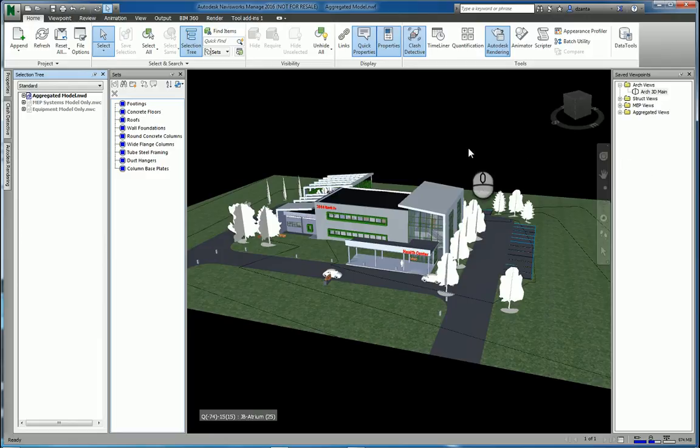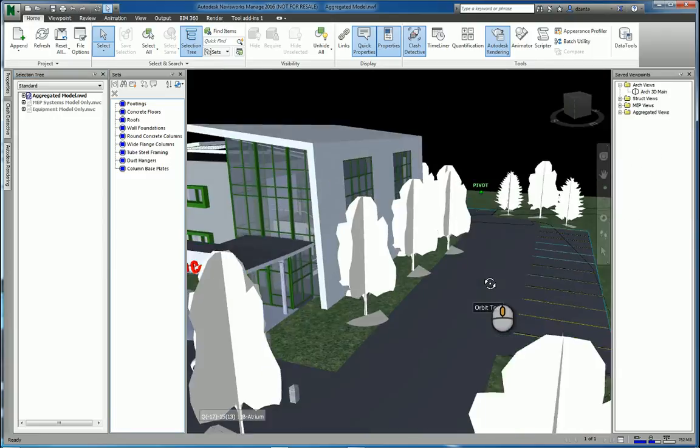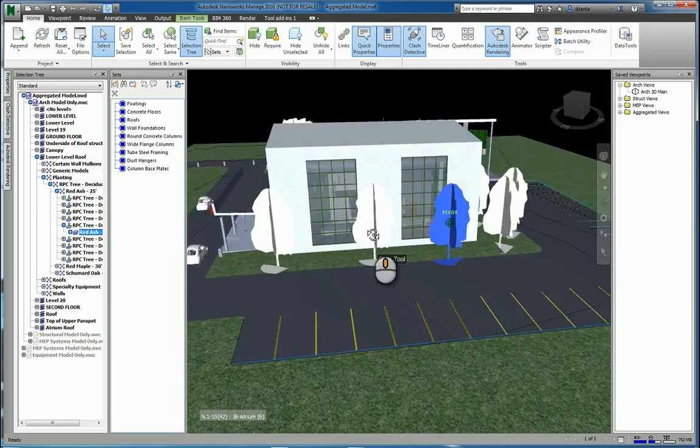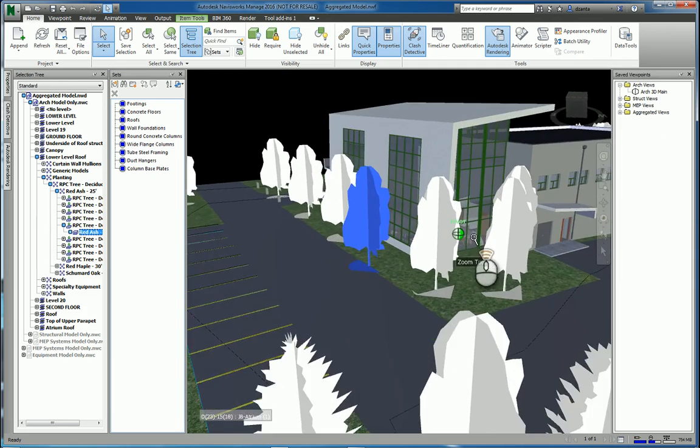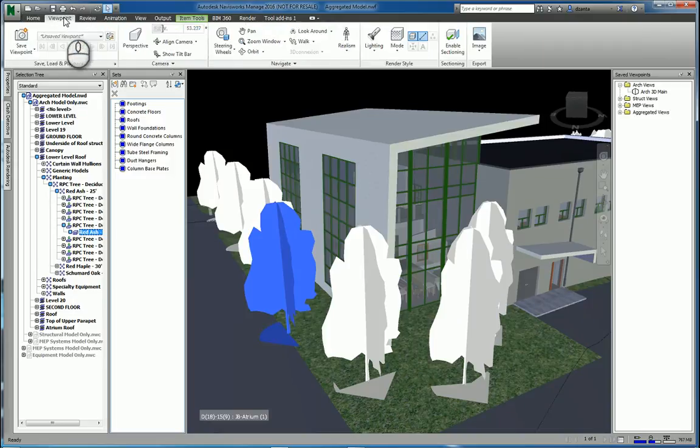One of the most useful features in the software, especially when you're just learning how to use the software, are ways for you to save the viewport. Let's say, for example, I need to zoom in here to a particular location. And I like this view for some reason. I can capture this view by just right-clicking over here under the Save Viewports panel. If you don't have that, go to the Viewports panel and click Save as well over here.